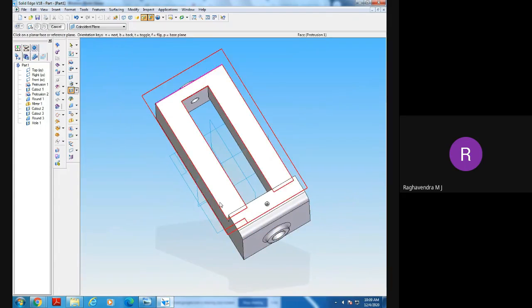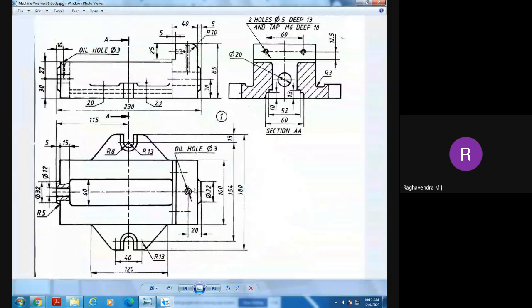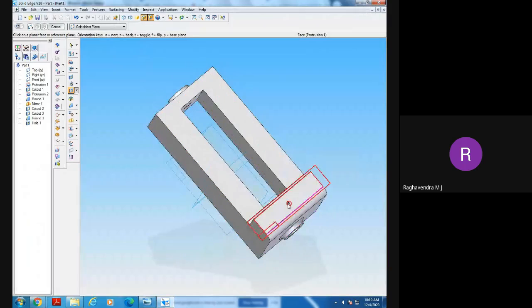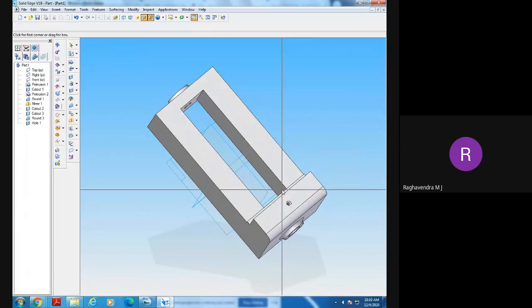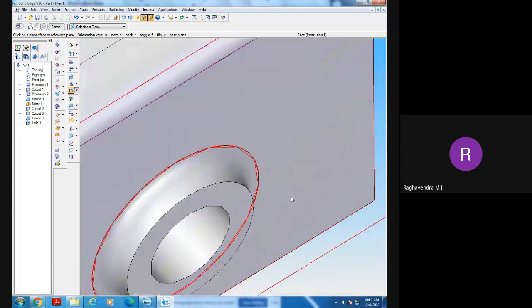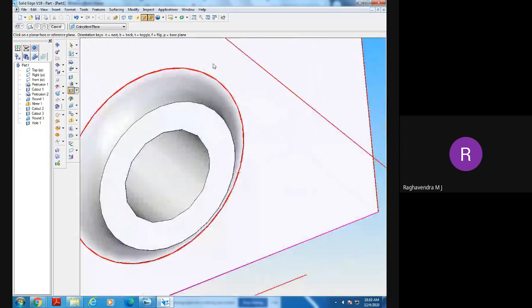Here the countersink diameter is not given. In this drawing, it is clearly not given. Approximately you do it, not a problem. It is for the pouring hole, for lubrication purposes. He has done some hole to pour oil through this hole, to lubricate these parts.